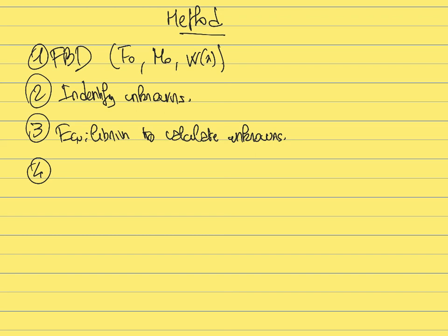So the first thing that you should look at in this case is, is there any discontinuity? Is there any concentrated force or concentrated moment inside the beam? If there is, then we know that this is going to induce some discontinuities in the internal shear and the internal moment.